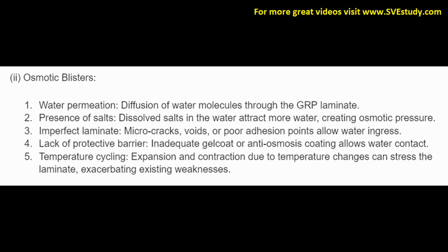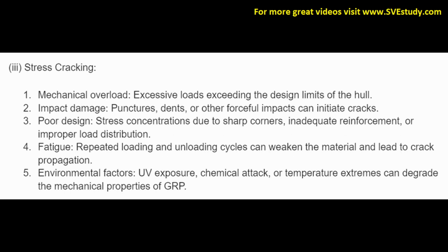4. Lack of protective barrier. Inadequate gel coat or anti-osmosis coating allows water contact. 5. Temperature cycling. Expansion and contraction due to temperature changes can stress the laminate, exacerbating existing weaknesses.